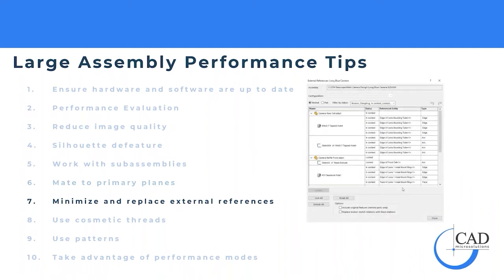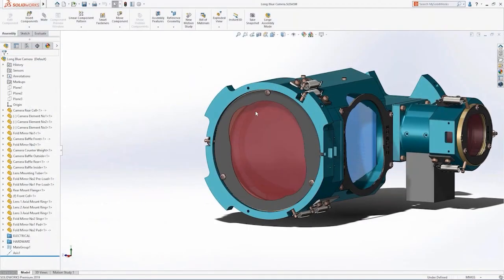We've talked about external references. They're a real trade-off. They're great for top-down design, and I really like them, but minimizing them is a great strategy. Something that I think is a little more attainable is starting with those top level external references in the top down design mode, and then using the commands available to us to reduce our external references. So that's what we're going to do here.